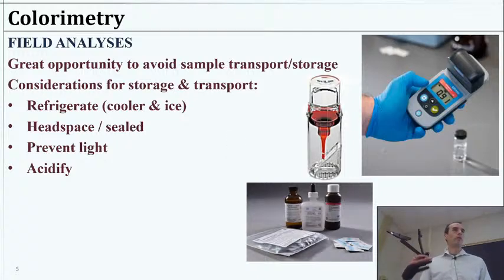The sample bottles, the coolers, the ice, where are we getting all of these pieces, right? Another part would be you may need to prevent light from entering your system. If you're worried about photosynthesis, if you're doing anything with BOD, for example, or if you're worried simply about your samples, maybe a breakdown of pollutants in there, right? There's a lot of photochemistry that happens if you leave water out in the sunlight. That will cause some changes.